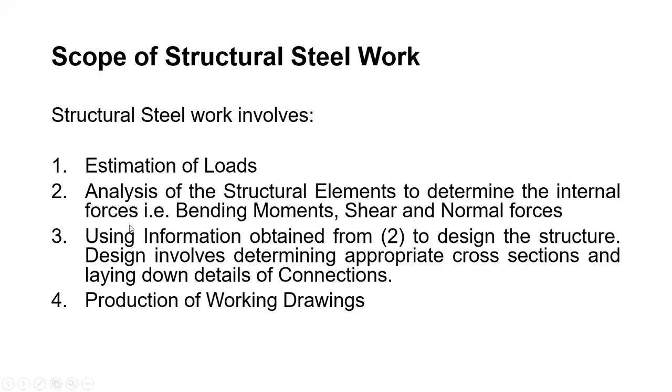The internal forces are the stresses. Common stresses used in design involve the bending moments, the shear, as well as the normal forces. All this has to be determined as the result of applying loads on a particular structural steel element.